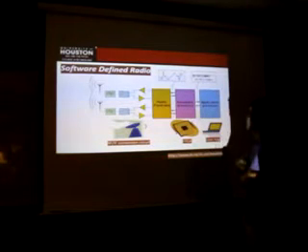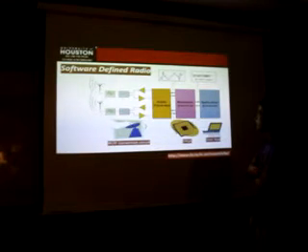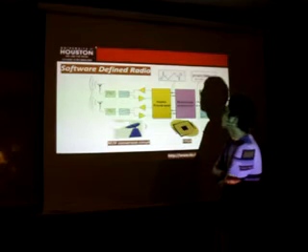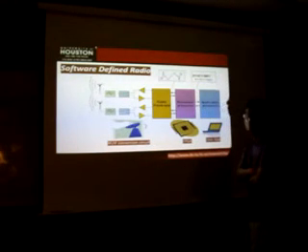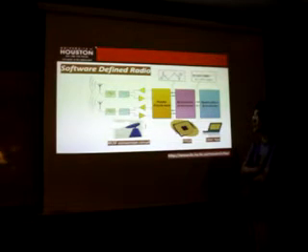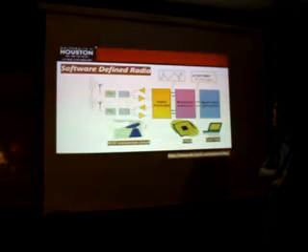The baseband processor is usually an FPGA, and the radio front end is the antenna and some RF and RF conversion circuit. RF means radio frequency, and IF is a low frequency signal, the intermediate frequency.